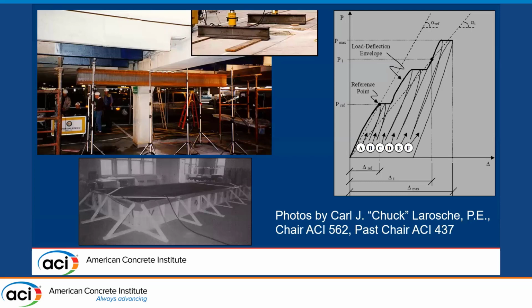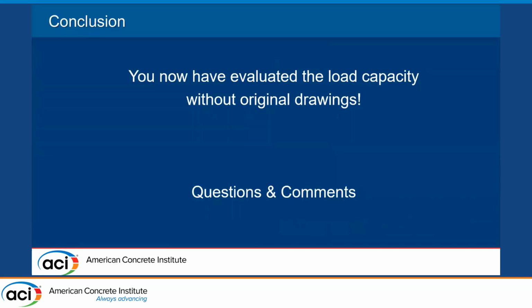That is a cyclic technique, which is allowed. It can get done very fast. Or the technique where you load it up to a level just really approaching yield stress, let it sit there overnight, and then you measure how much deflection has occurred, right? Both techniques are good. One you stay up all night with the structure, the other one you get done quick. So these are really good techniques, and I found building officials like results from load tests because it's a load test. You actually loaded it.